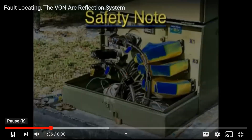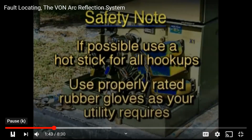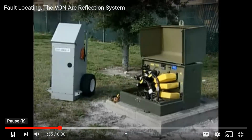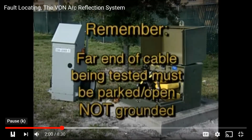But before we begin, here are two safety notes. If possible, all hookups should be performed using a hot stick and or properly rated rubber gloves, depending on your utility's requirements. We'll illustrate the hookup on a typical dead front pad mount transformer. Before you begin, remember the far end of the cable being tested must be parked and or open, not grounded.